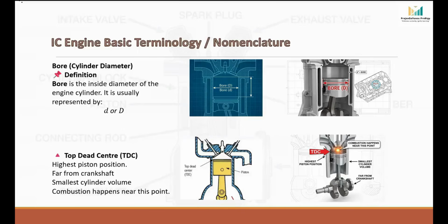Excessive wear may damage the piston rings or even piston, and it may create the liner scoring or major engine failure. So bore is not just a dimension, it is critical parameter for engine health. And that's why during major overhauling, bore measurement is mandatory.